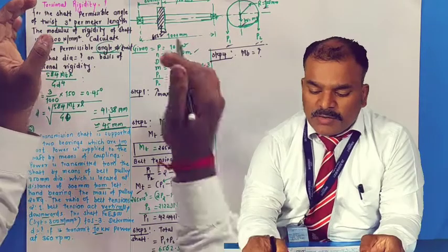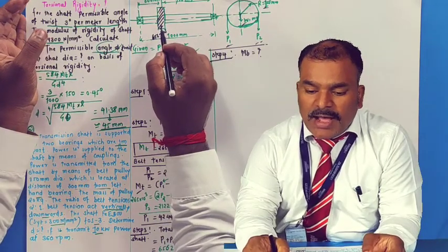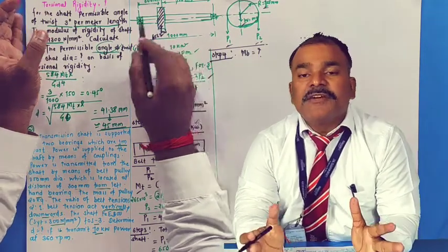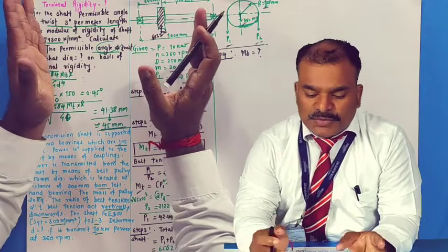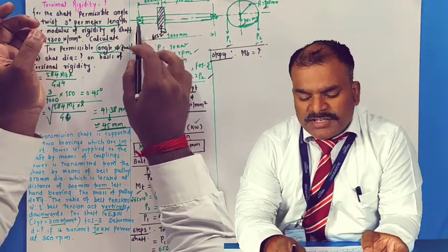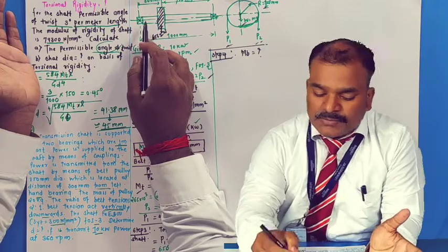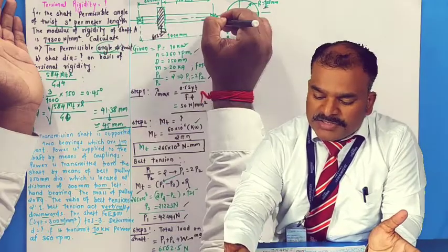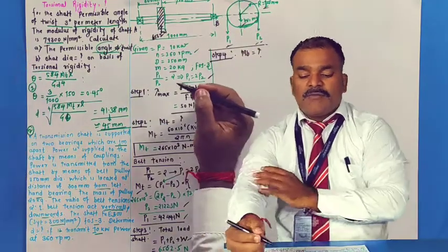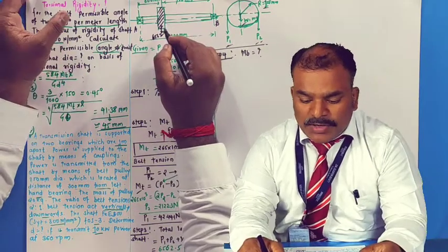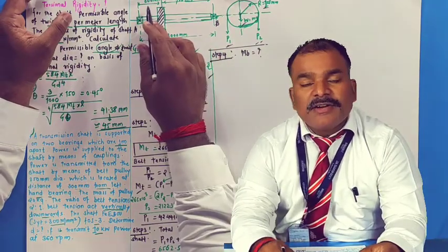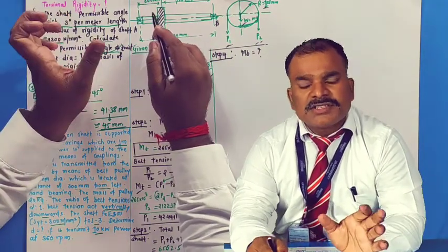Of course, while calculating the bending moment, I will have to select which end will bend. So see, 300 is the distance from the left hand bearing. I'll say A bearing, and B bearing on the right side. Now while calculating the bending moment, I will have to consider 300, but it is the shortest distance.